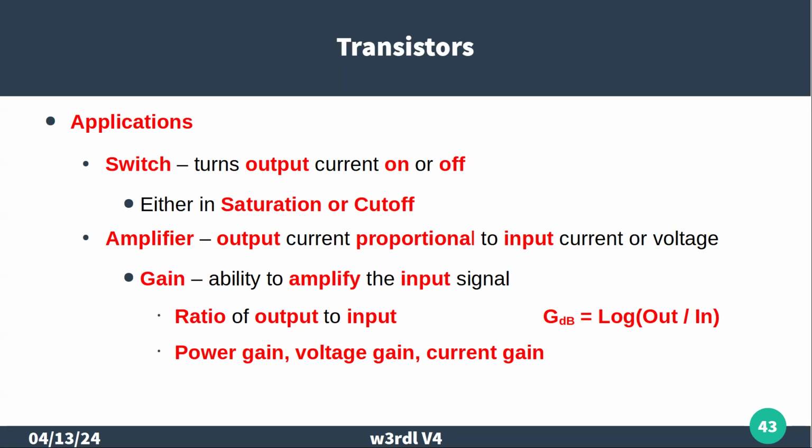And the signal on that control element will control the current through the device proportional to it based on the gain of the device, or the beta, which again is proportional to, in the case of the junction transistor, how thick that layer is. So the thinner you make it, the higher the gain, but then also the lower voltage that it can operate at, because at some point you would break over that region.